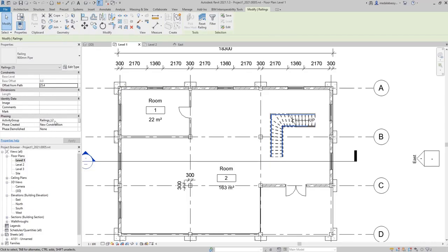That's because there is a shaft that's cutting to the slab in the middle at level 2. So when we select from level 2, we're actually selecting everything for level 1 and 2. But since we're at the lower levels, we will only select those from the previous selection. And then we can just change it to L1. And click apply.